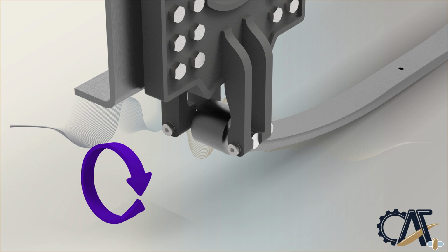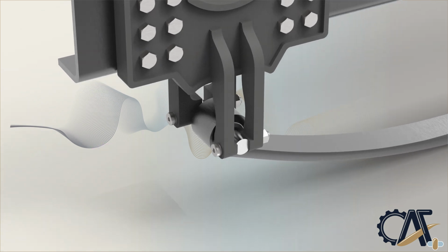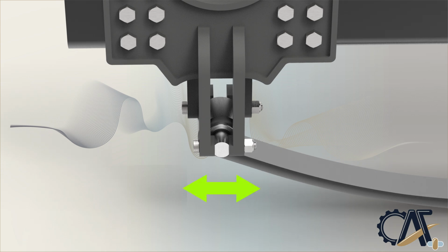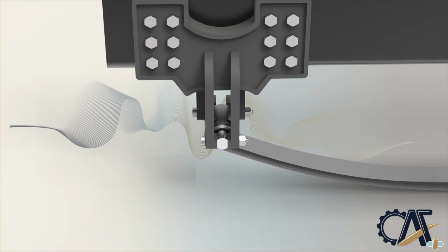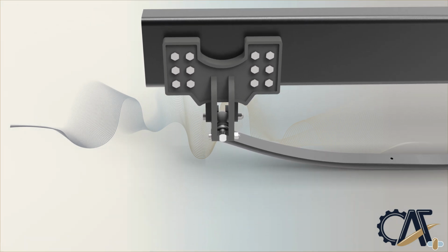Now you can see the leaf spring is twisting. The conical degree of freedom of the bushing enables the spring to perform such motions. The twisting of a leaf spring can happen due to the chassis twisting across articulation loads imposed on the axle of the suspension. The normal deformation mode of the bushing enables the spring to move fore and aft during the braking and acceleration of a vehicle. Lastly, the radial deformation mode of the bushing well connected to the leaf spring is demonstrated. This deformation mode occurs during vertical load to the axle of the vehicle.